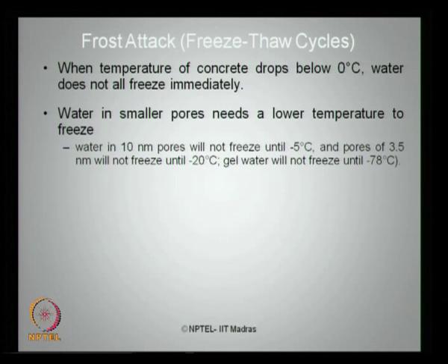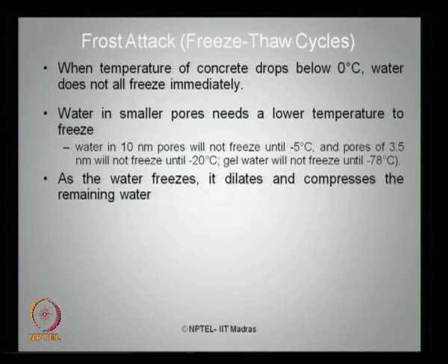So, water in 10 nanometer pores will not freeze until -5 degrees is reached, and pores of 3.5 nanometer will not freeze until -20 degrees is reached. Gel water will not freeze until -78 degrees Celsius is reached. So, water does not freeze immediately as soon as temperature drops down to 0.